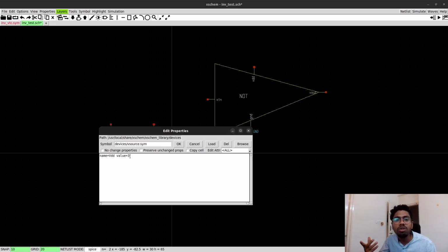How do we know that 0 won't work? From our previous steps, Episode 2. Try with VDD 0 and give any VGS. You will get 0 output. So from there we know that 0 won't work. Use the biggest number, which is 1.8, which is supported.